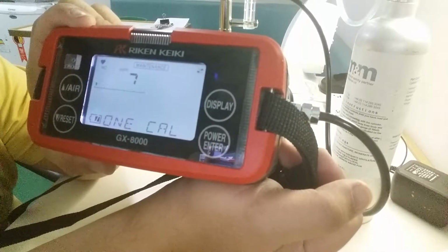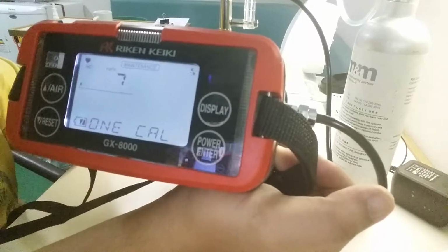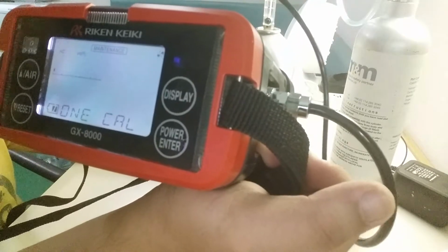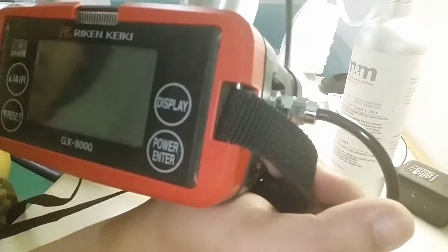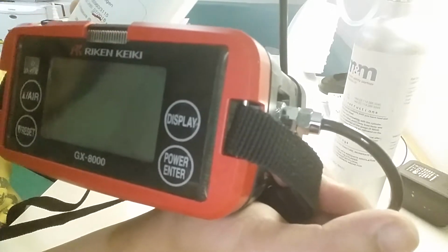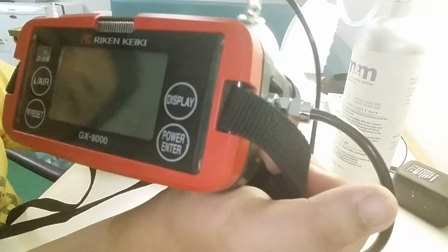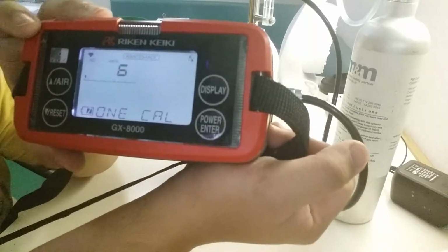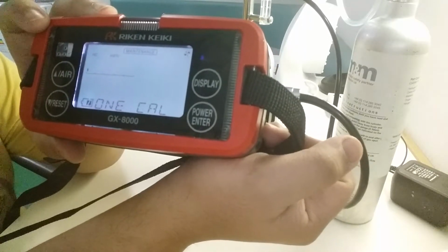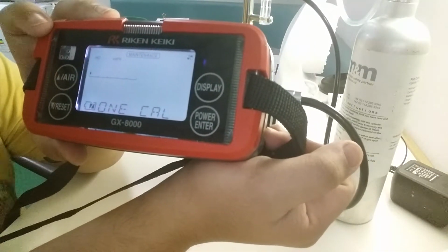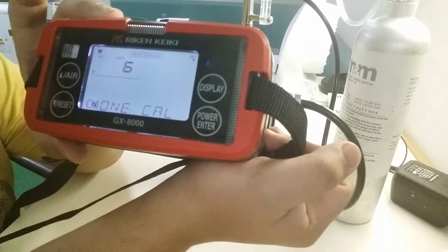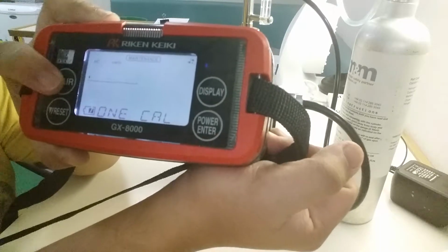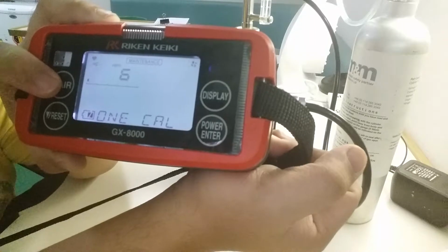So the volume, which is our target, is 8%, as I'll show you. As I've shown you on the gas concentration, our span gas is 8% volume. So we just wait about 60 seconds and we will see if the equipment is stable. So it's reading, let's say it's already stable and it's already 60 seconds. So we will adjust according to the span gas